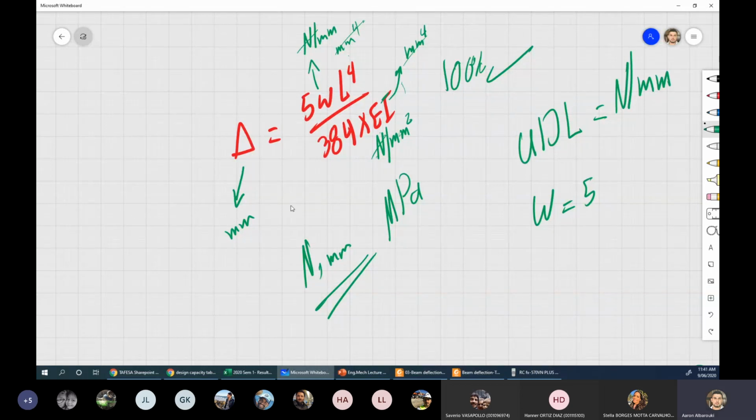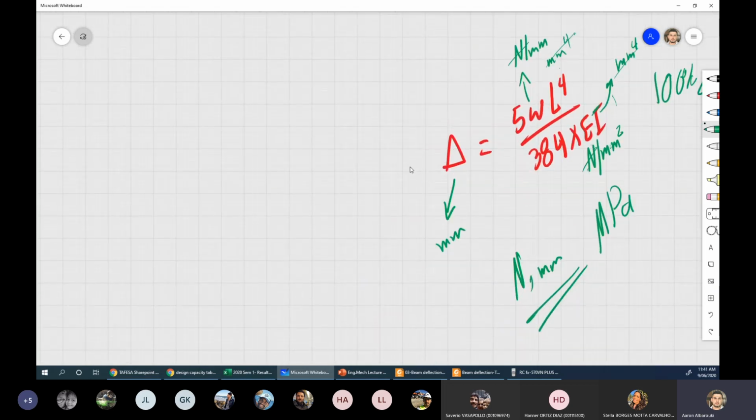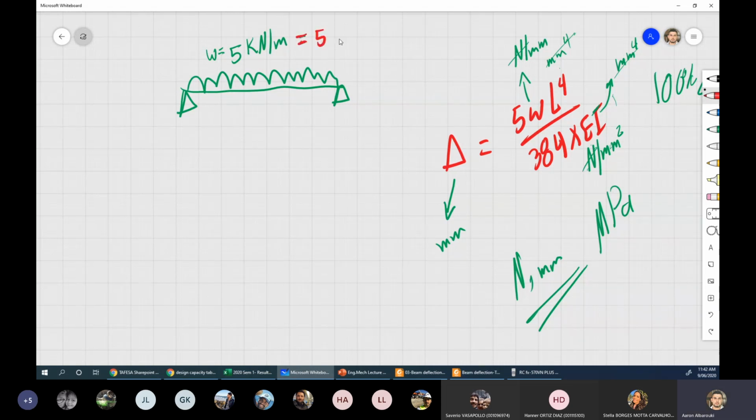W, never in newtons. For some reason, I put it as a point load in newtons. In W, when I give you a beam, that was a shock in the morning. You guys made me rethink my calculations for the last 10 years of engineering. They all should be wrong based on what we came up with today. So if I say I've got a UDL W equals 5 kilonewton per meter, in other words this is equivalent to 5 Newton per millimeter. This is divided by 1,000, this is multiplied by 1,000, this is multiplied by 1,000, so they cancel each other. So my units here: Newton per millimeter, millimeter power 4, Newton millimeter square.